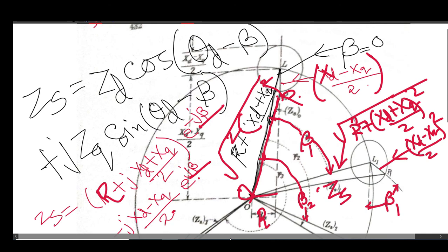So it is obvious that the armature reaction MMFs, both AD and AQ, are also rotating at synchronous speed along with your field winding. Your field winding is continuously rotating at synchronous speed, and these AD and AQ are fictitious armature reactions, which means they are not real.